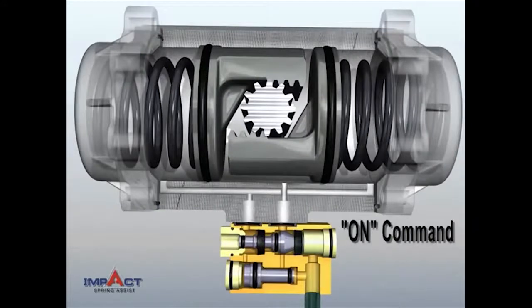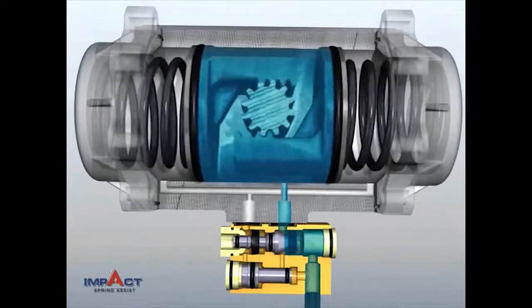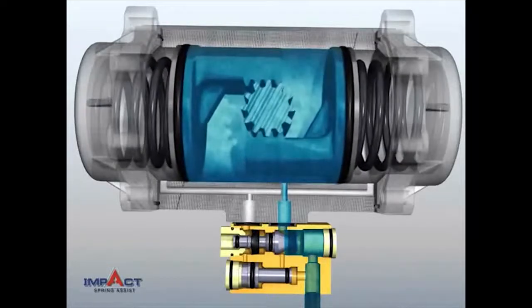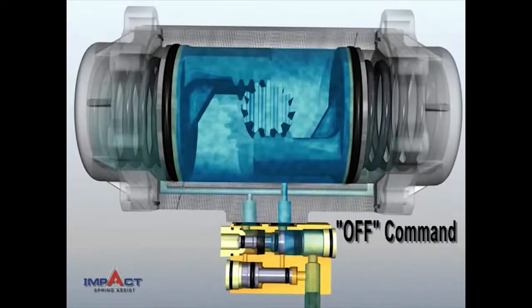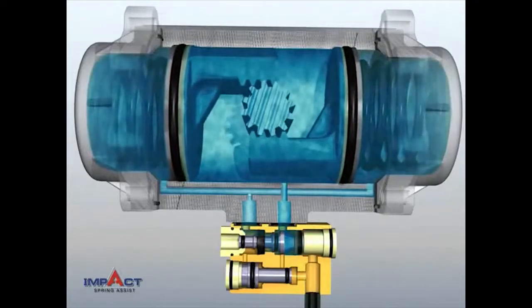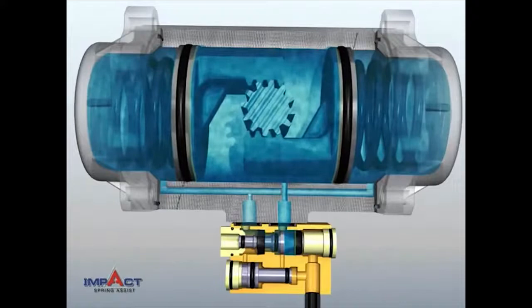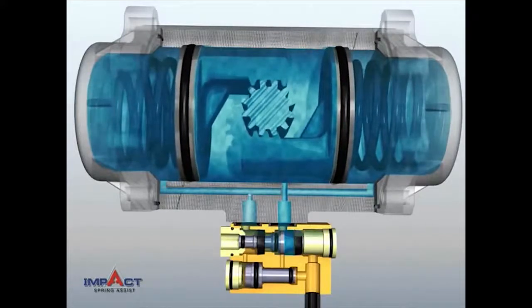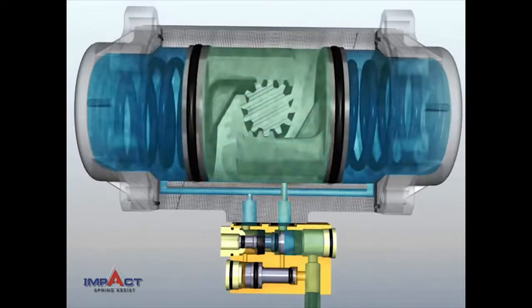This is a spring return pneumatic spring actuator. And so you guys can see this is the first port down here. And the second, this is only one port because it only lets fluid in one way. So when you let fluid in, it goes into the middle and it pushes this bladder open. And so it'll turn those cogs and those gears, and it'll turn that ball 90 degrees for you. When you take air out of that and you suck it out, the springs want to force that thing closed, and so it'll close automatically.